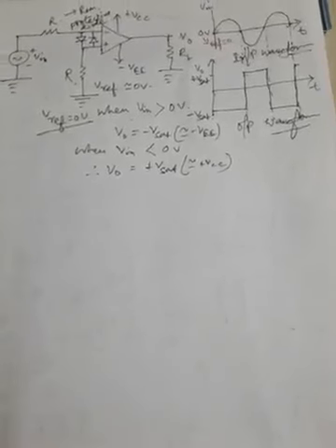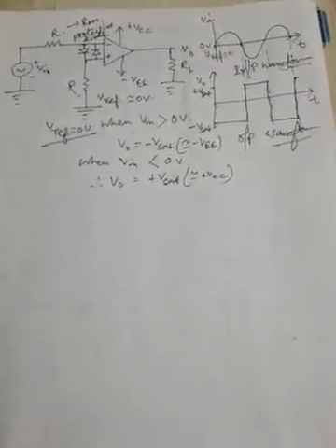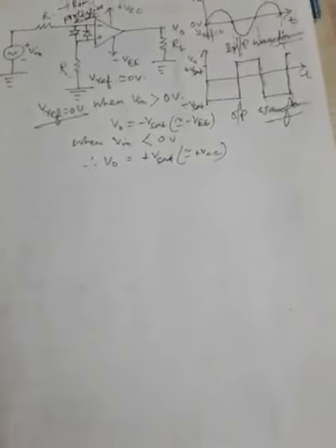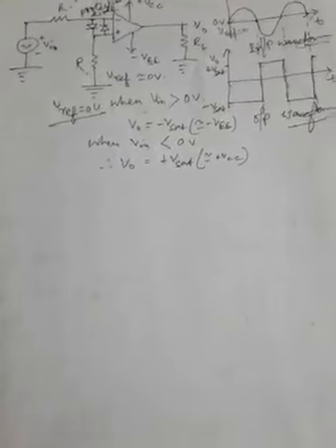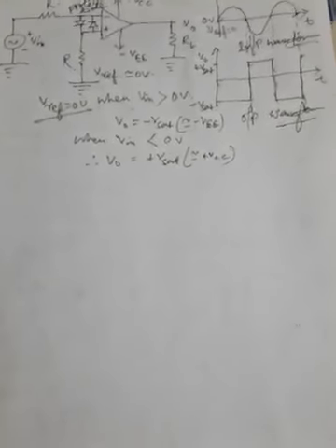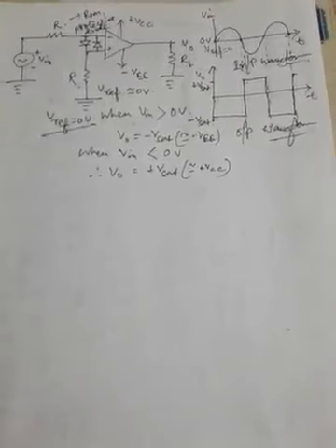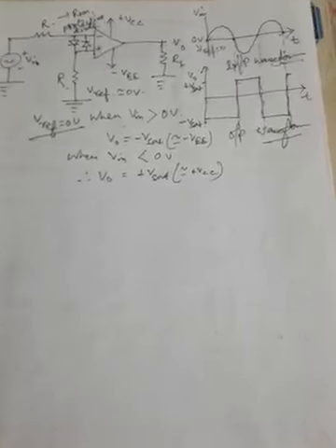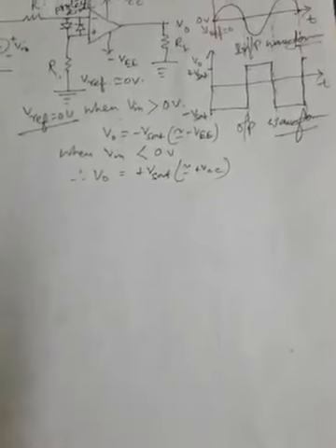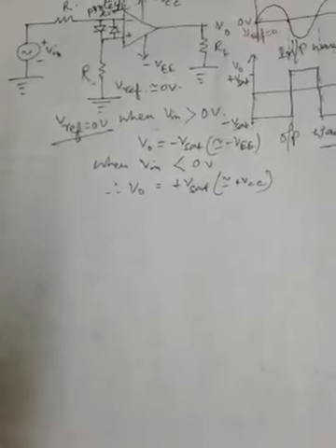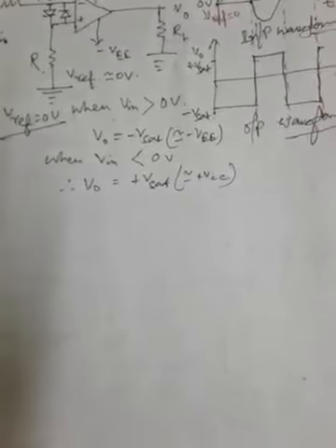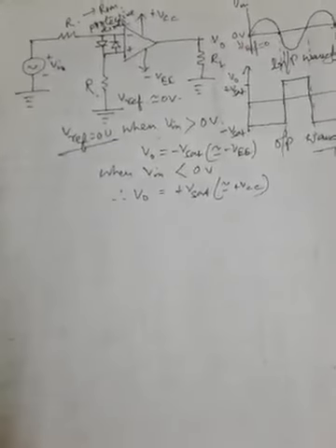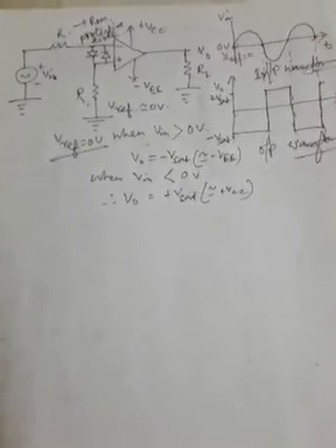Okay, so both of these problems can be cured with the use of positive feedback or regenerative feedback in this circuit. As this circuit is working in open loop, there is a possibility of using feedback, and if it is positive or regenerative feedback, that causes the output VO to change faster rather than being slow, and thereby it will eliminate any false output transitions due to noise signals at the input. So the slow change will be cured because of using positive feedback, and that will make the circuit work faster, so that the output switching between the two saturation levels becomes fast, and therefore the noise problem and the slow changing waveform problem of V in may be countered.